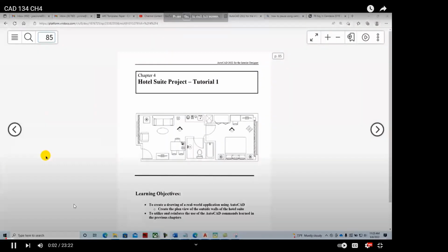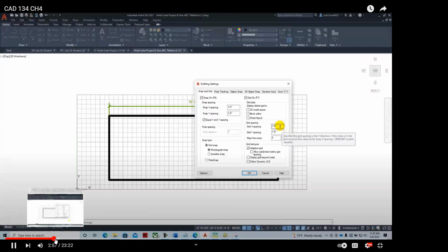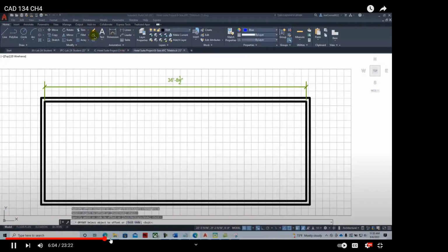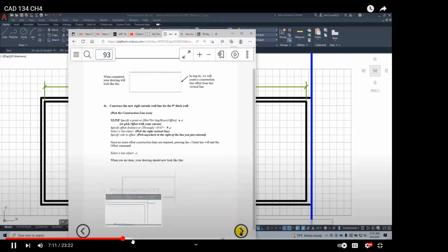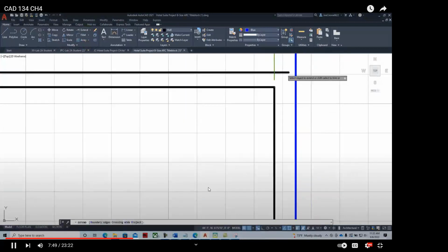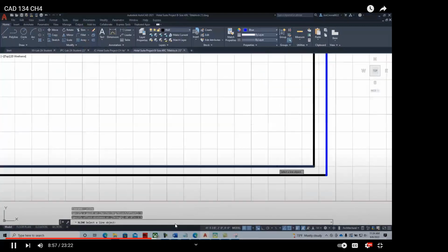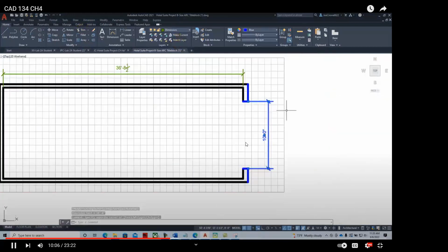And in the video, we walk you through the basic construction processes. When I created this drawing, I tended to use lines instead of construction lines, but they really work very similarly. And so we'll go through with some of Joe's techniques versus some of the textbook authors' techniques. But essentially, you start off by drawing this rectangular shape. You explode that rectangular shape, and then you offset the lines, and you create the geometry for this opening right here, for this window.